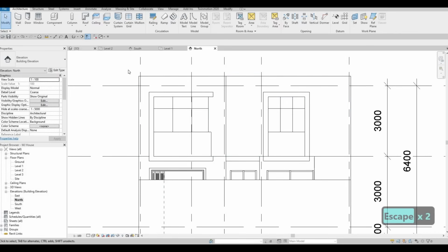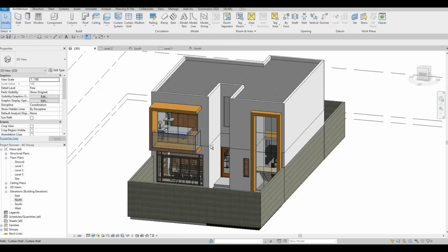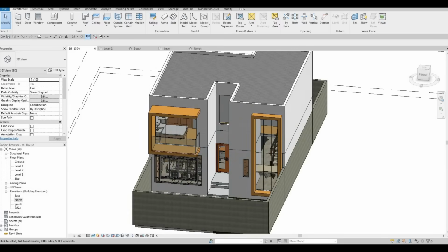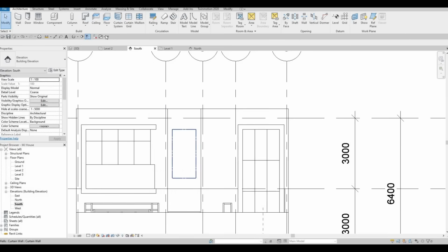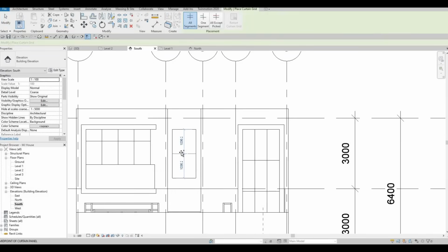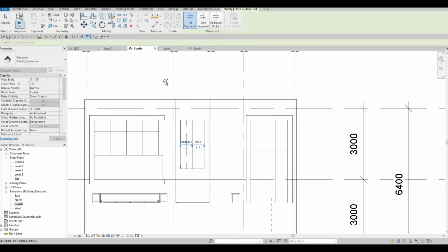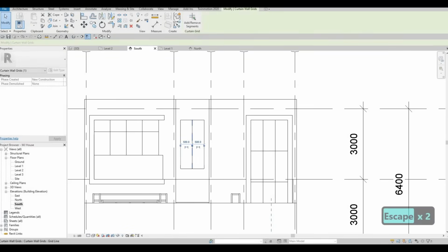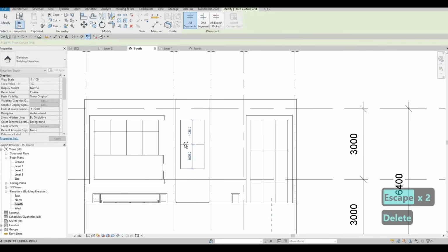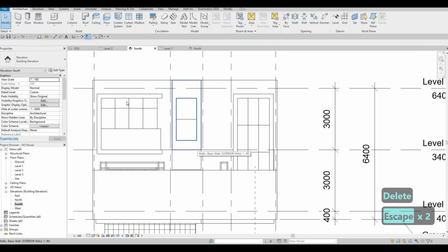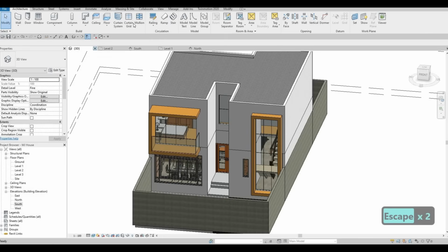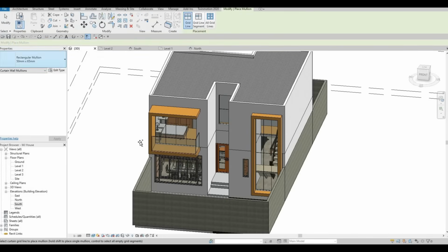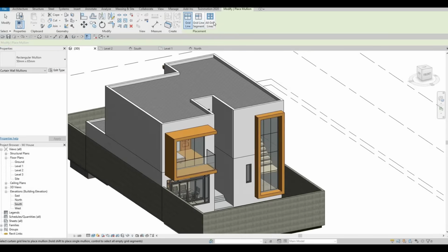And then now let's go to 3D to look into it. For the one that is right here, what we could do is we could just maybe divide them, something like that. Or I think it's better if we just do it in half, something like that. Let's go to 3D, click on mullion, and then choose 50 by 65, and then all grid.